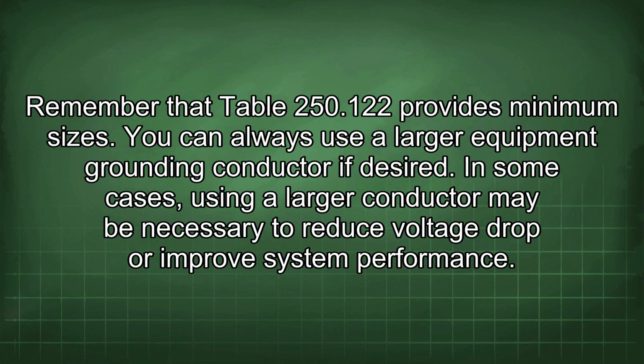Remember that Table 250.122 provides minimum sizes. You can always use a larger equipment grounding conductor if desired. In some cases, using a larger conductor may be necessary to reduce voltage drop or improve system performance.